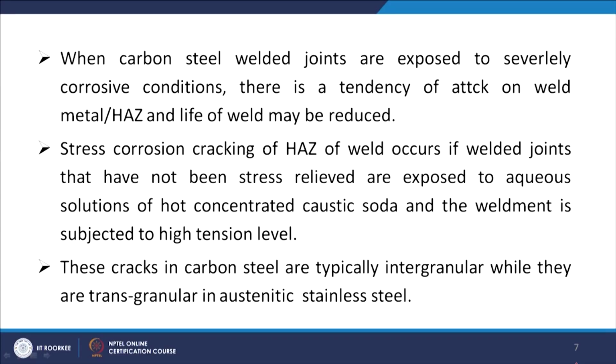So, when these carbon steel welded joints are exposed to severely corrosive conditions, there will be a tendency of attack on the weld metal or HAZ, and the life of the weld metal may be reduced.